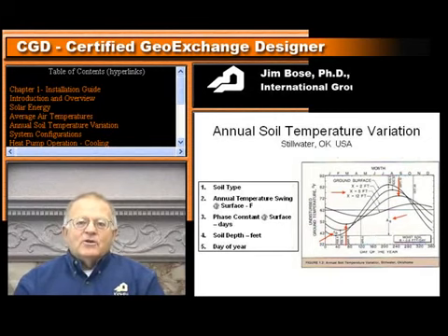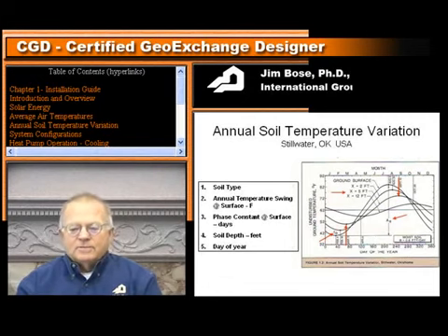Kind of as a guide, you can say that if a blue norther came through, that temperature would be reflected about 4 weeks later if you were at 4 feet. So about 1 week delay for each depth of soil, each foot, that you go down to. And also these curves are dependent upon what kind of soil you have. If the soil is drier, well then the amplitudes and the phase shifts will change.